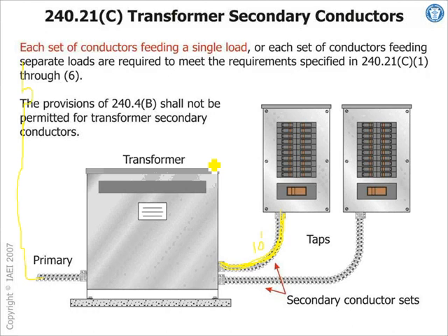Okay. Now, what size conductor for 10 feet or more? What minimum size conductor do I need right here for a 10-foot tap? The reason I say this is because do you see any circuit breaker here? Nothing whatsoever. The first circuit breaker is sitting right here. So what's the smallest conductor that I can tap out of this transformer without an overcurrent protection device?